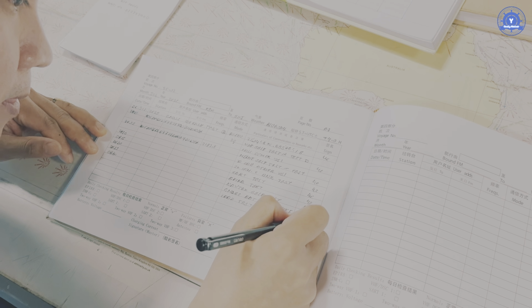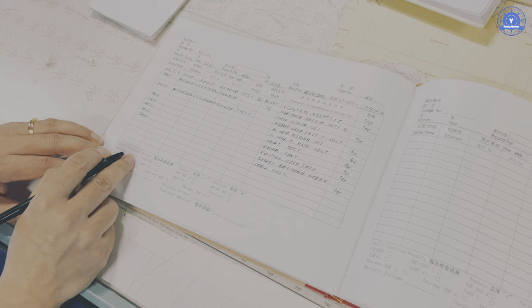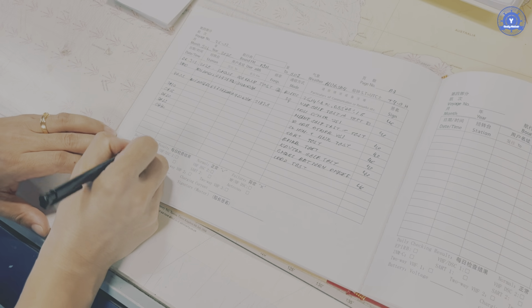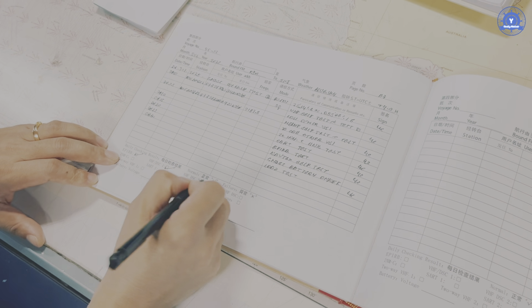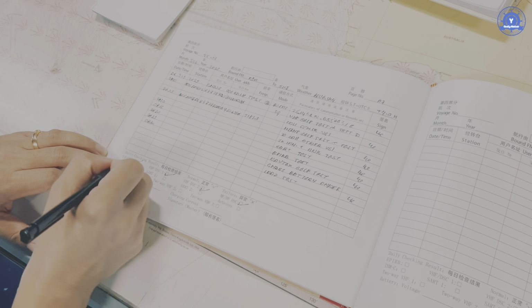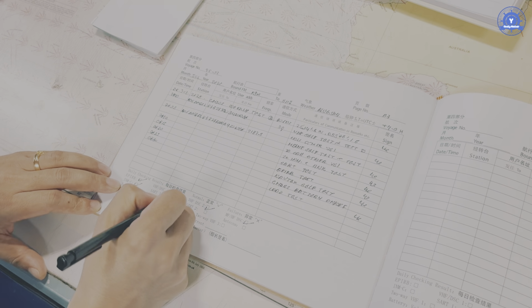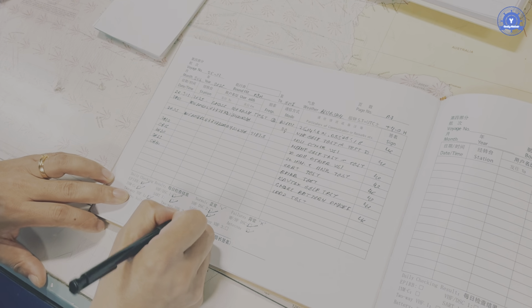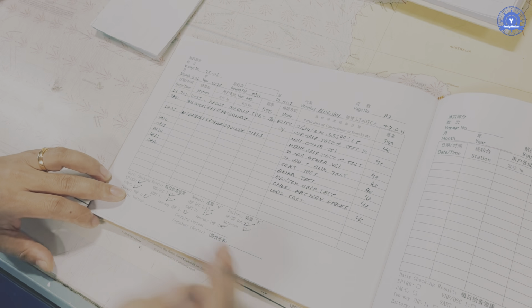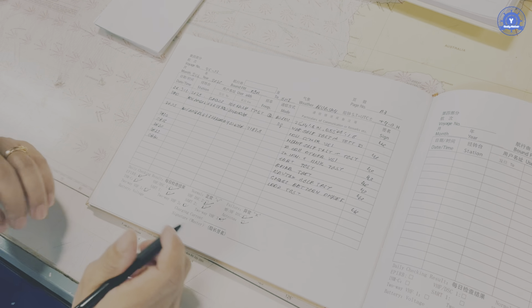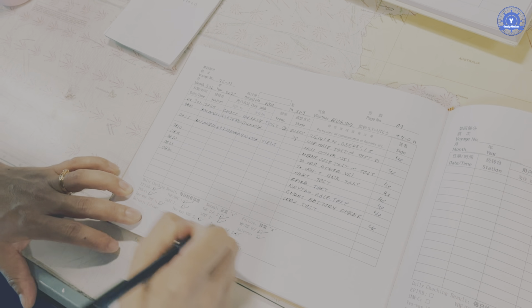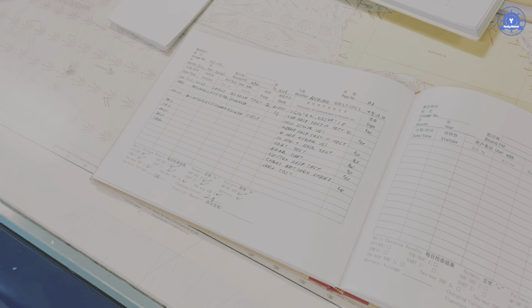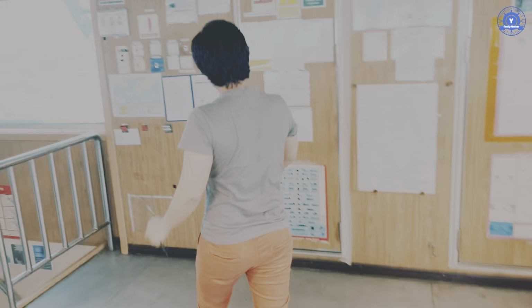logbook. And then from here daily check-in result, so that's it, normal dish, and then failure cross, so that's the IBAT. Okay, Voyager DSC 1 okay, Voyager DSC 2 okay, Voyager DSC okay, and then emergency okay, sub 1 okay, sub 2 okay, antenna okay, and two-way Voyager 1, two-way Voyager. This two-way Voyager is for monthly, the two-way Voyager antenna need to check monthly and pivot departure. So and then battery voltage 24 volt around 0.9 current, and then from here signature of master, and then that's we need to check the GMDSS battery.